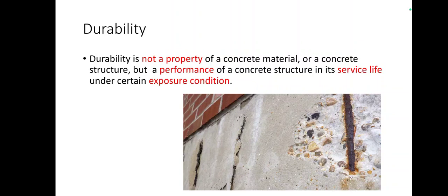The cube placed inside the room will be more durable when compared to the concrete placed outside. The outside one will have some damages. Why? Because its exposure condition is different. The amount of rainfall, the exposure to heat and sun rays will be different from when the concrete is placed inside the room.